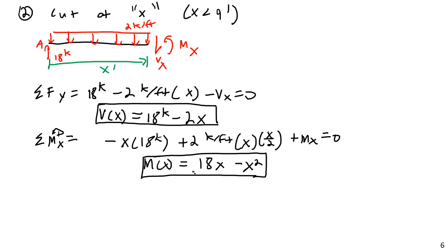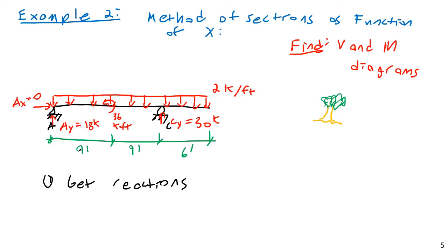But of course, there is a direct differential relationship. I will see later, of course, and remember from statics that the derivative of moment is shear. Okay, so next I want to cut at x when x is between 9 and 18 feet.